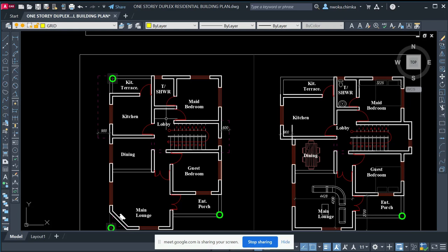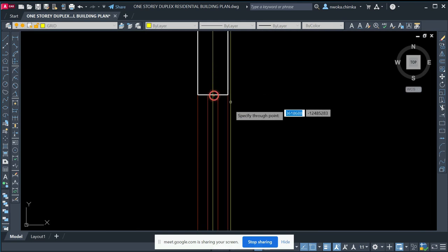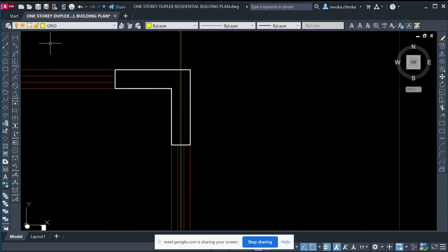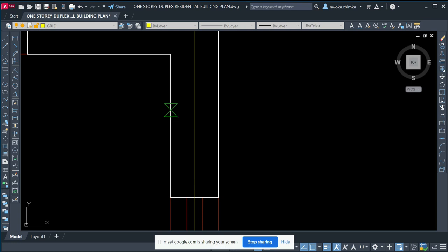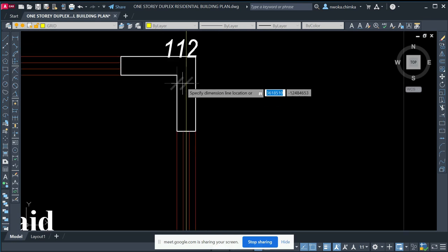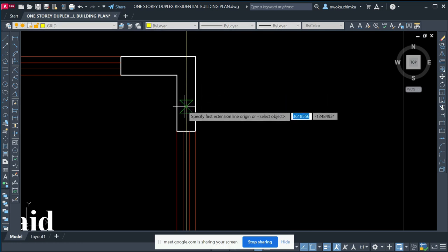Okay, so right now I want to create all my vertical grid lines. I'll type XL, enter, and V, enter, and then place it at the midpoint here. When I do that, I have to confirm that this line is at the center, so I dimension just one here. This gives me 112, and if the other side is the same, then it's centered, because the width of this wall is 225.